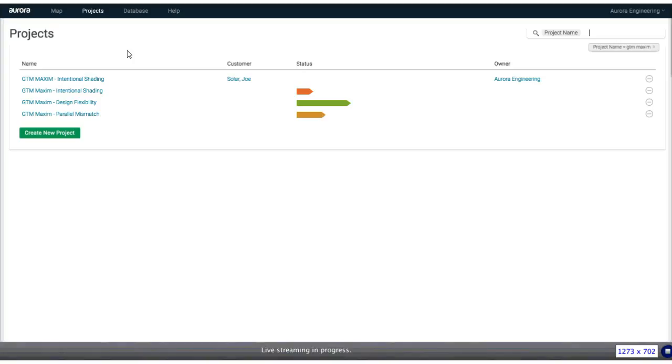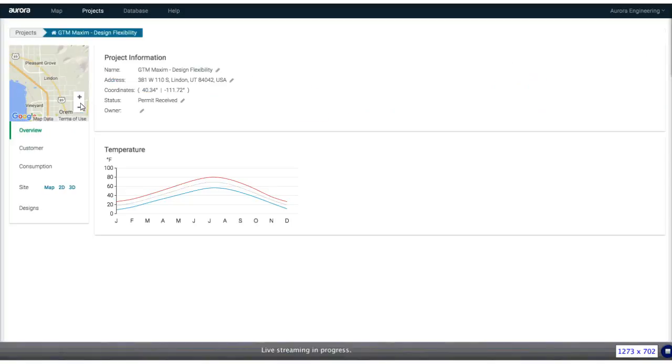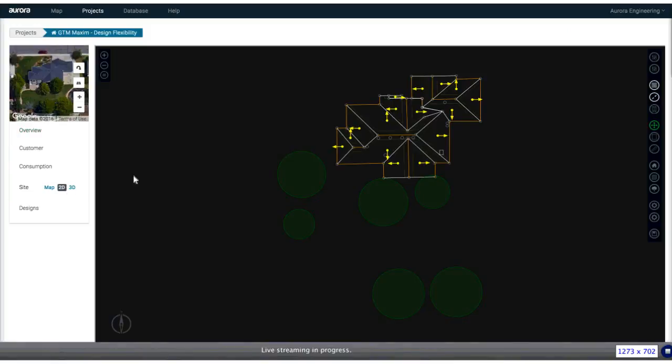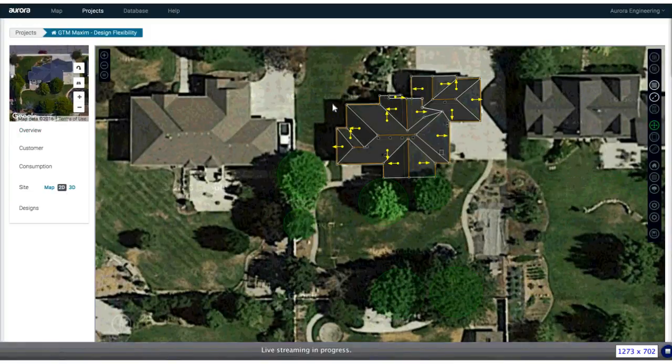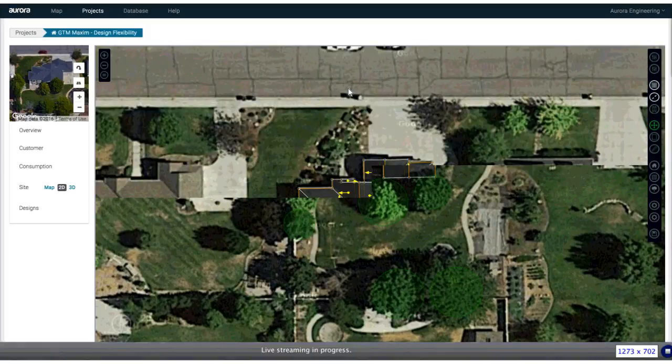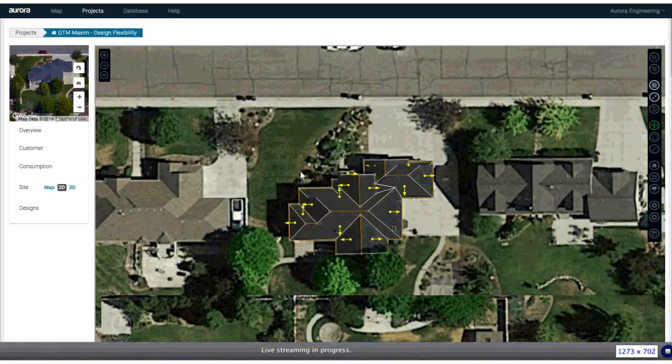And also with bypass diodes, in traditional modules, at best, when we use them, we just cut out that module, so it contributes no power to the total. Whereas with cell string optimizers, even if a module is in shade or just outputting less energy, it's still producing energy and adding on to our total. So we're still gaining some performance boost there.